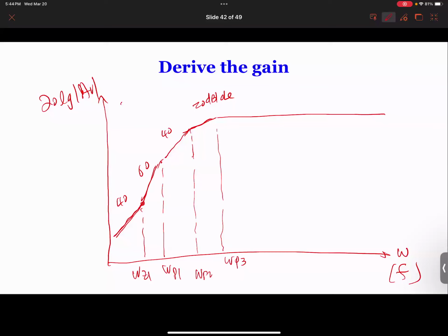You have 3 poles, 3 zeros. So now you remember, for low frequency response, how in the future do you identify whether it's low or high frequency response? For low frequency response, there's always a zero, there's always a pole, so that when S is small, it has an impact. When S is big, you can cancel S on both numerator and denominator. So for low frequency response, there's always an equal number of poles and zeros. That'll make it a little easier.